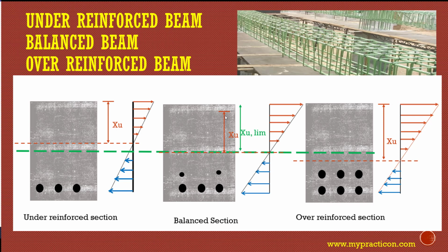Whereas concrete is weak in tension and strong in compression. So that's the reason we introduce the reinforcement in the tensile zone to take care of the tension, and in the compression zone, concrete will take care of the strength effectively. So since we are introducing the reinforcement in the concrete, we call the entire cross section, or the entire beam, a reinforced concrete beam.